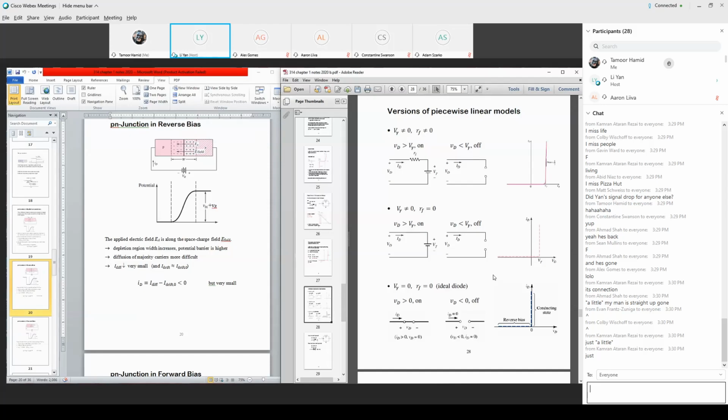Physically the voltage must be greater than 0, but we model it as having a finite current that starts shooting up at voltage equal to 0, because this straight line is not tilted but increases vertically. This vertical increase is actually at V gamma, and we model it at V equal to 0. Okay?